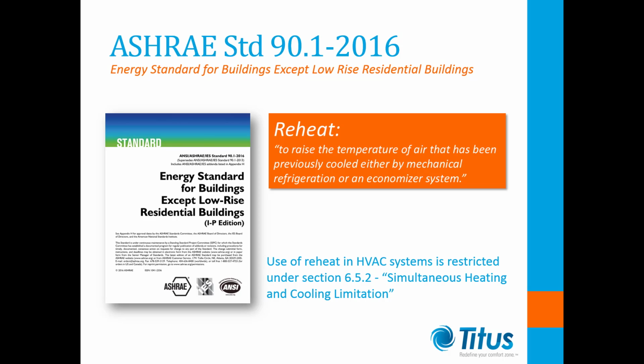But reheat often occurs with traditional HVAC systems, as air is used to perform three separate tasks: ventilation, dehumidification, and cooling. This multitasking causes some problems. Some zones in the building may require high amounts of ventilation air and very little cooling. But the temperature of the air must be set low enough to satisfy the zones which have the highest cooling demands. So zone heating of pre-cooled air will now occur in the spaces that have low cooling demand to prevent overcooling.